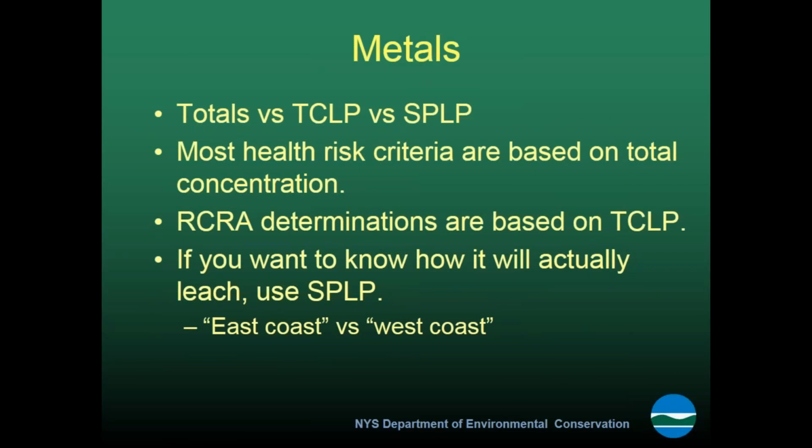There are a few different ways that you can test for these metals. Most of the health risk criteria are based on the total concentration of the metal in the soil. So if you're testing for lead, you might have a certain 10 parts per million or parts per billion of lead in the soil. If you're looking at characterizing the soil for waste disposal, and that would be relative to the RCRA requirements, you'd need to test the TCLP,